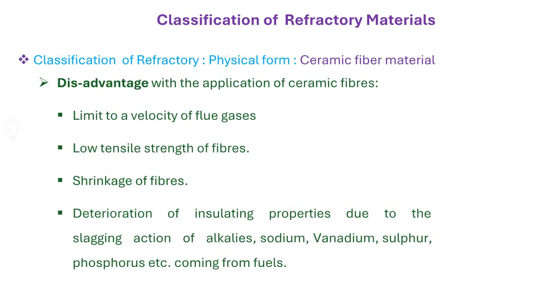While ceramic fiber offers many advantages, it's equally important to understand its limitations. Let's go through them one by one. First limitation: velocity. Ceramic fibers can only handle a certain flue gas velocity.